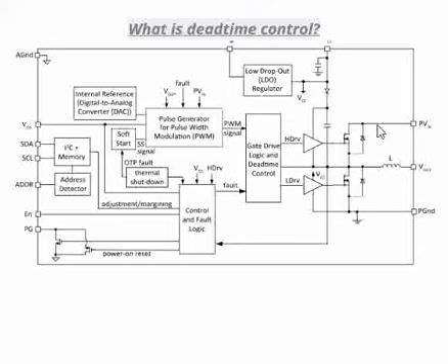So you see a direct shot between the power and the ground, which brings in a scenario called shoot through. Shoot through is like a large surge of current passes through this because there is a short of these MOSFETs, right?